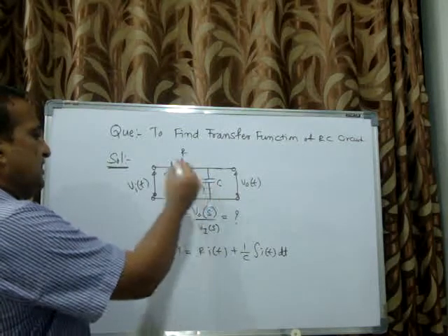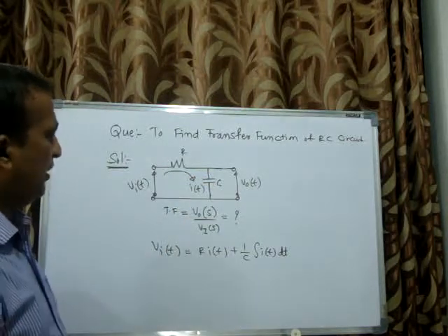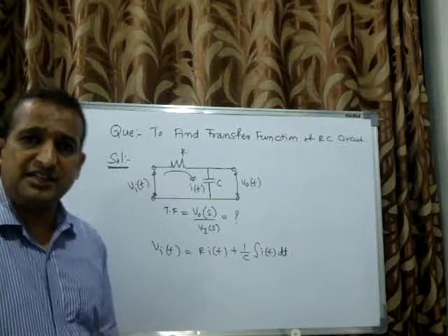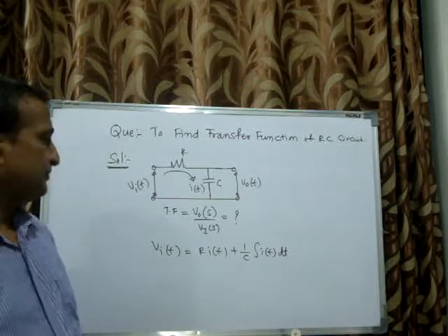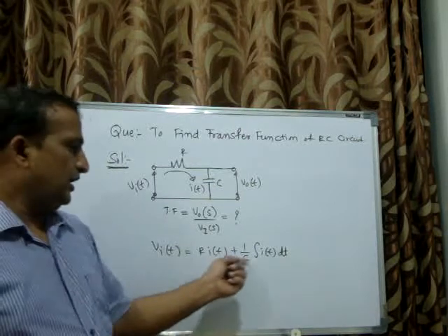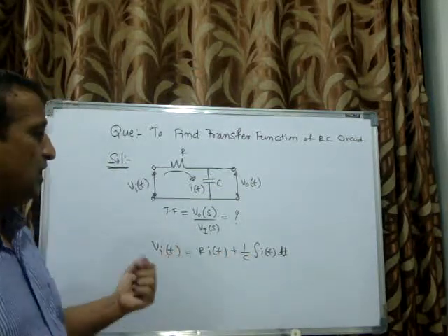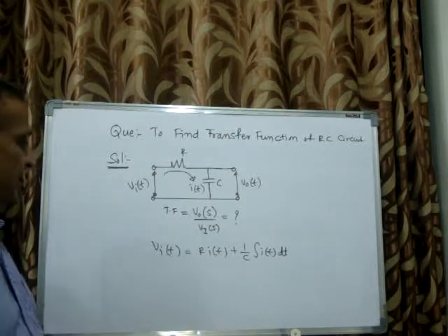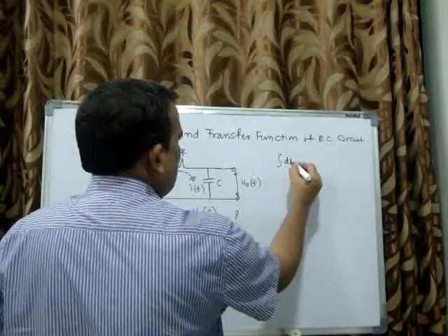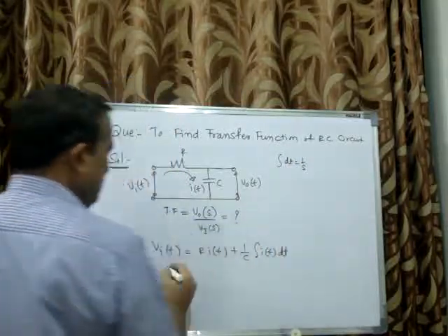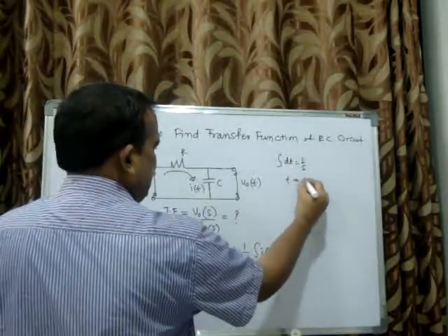Okay. These two are the resisting elements. Even all three, inductor, resistor and capacitor, resist the motion of electrons. So here if you see this, you get an integral equation. How to overcome the integral equation? Taking a Laplace transformation. We know that integration of dt is how much? 1 by s. So now I will write s for that.